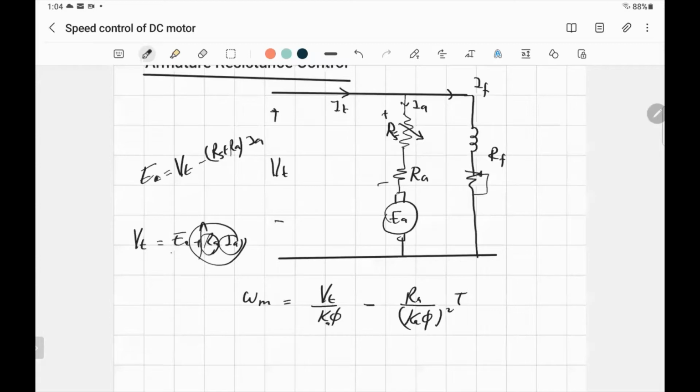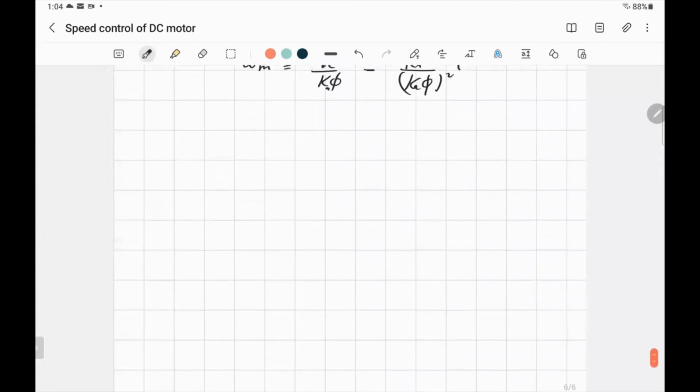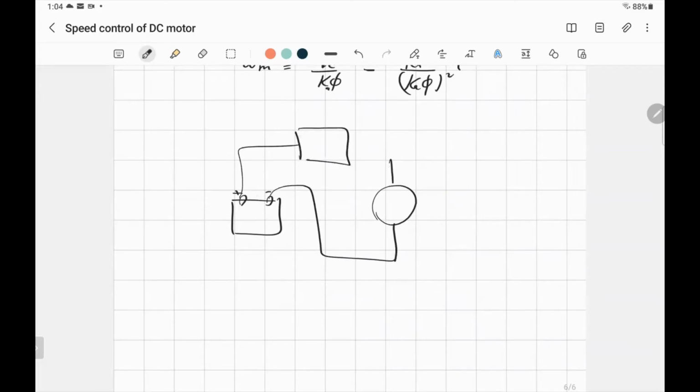And they still use it in small motors, but power electronics replaced that. They are using a technique called pulse width modulation, by controlling the voltage. You have the battery there, 12 volts or 120 volts, whatever, fixed, but there's a converter. If this is the battery here, positive and negative, and then this is the motor that you have, and then the positive here we have something called a chopper or a switching regulator.